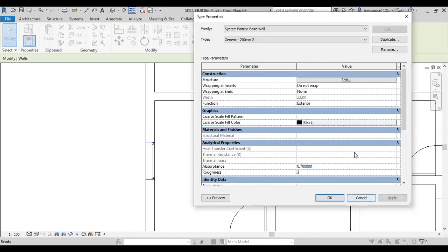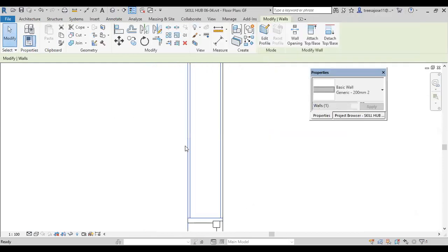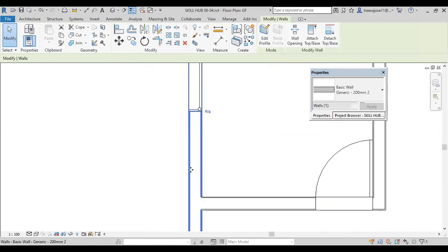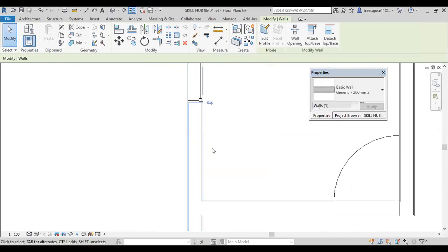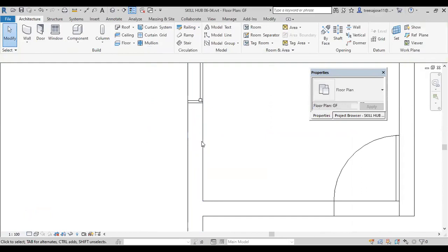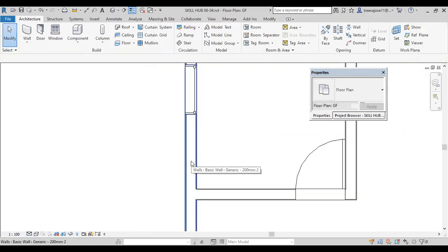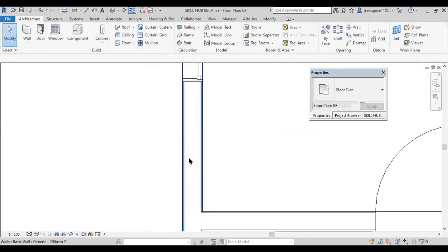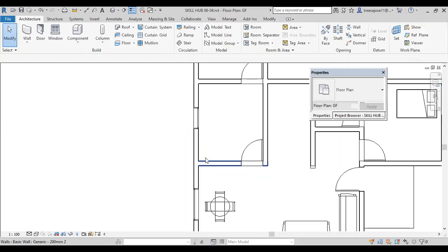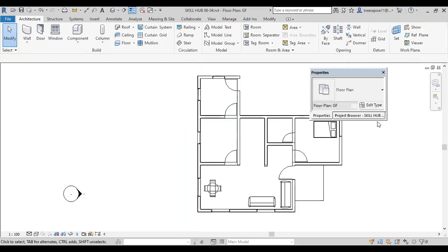Okay. Immediately the system will show that detail. Then if you need to see it this way, you change the visual style. Coarse means only the outer shells will be indicated. Then you can change these. So fine. Okay. This way, in the case of working drawings and all, we can use that. Then it is possible to dimension each and every part also. Okay. This way you can change the views.